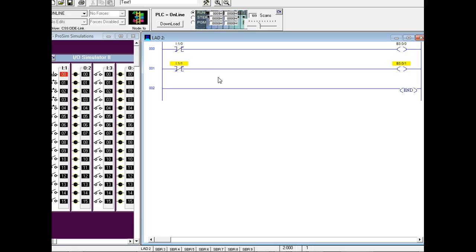I mean, when you compile a program over to your PLC binary language, all it knows is the syntax. And what is syntax, by the way? S-Y-N. It's the way things are written. Of course, in PLC language, it's drawn. And that's all it can check for, is if it's drawn correctly. Not if you meant to use a counter and you put a timer in there. Is it going to give you an error? No.